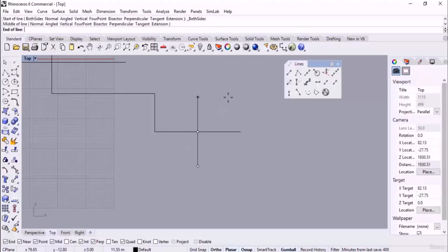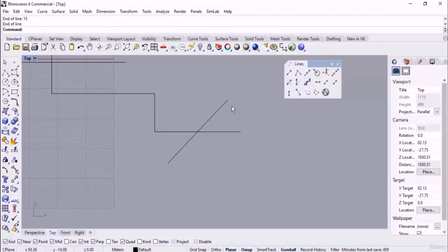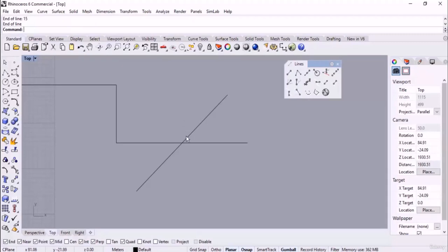And I have explained specifying the angles, for example, 45 degrees and 50 meters for length. At first the less than symbol, 45 enter, then the length, the angle is specified. I specify 15 enter, very well. Then I specify the direction, and this will be the result. The 15 degrees is related to the half of the line, from the midpoint to the top part, and from the midpoint to the bottom, or the other end of the line.